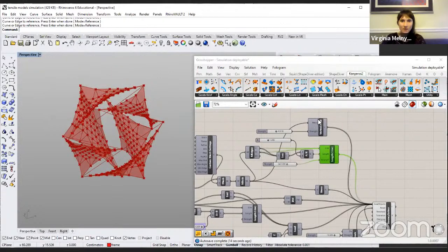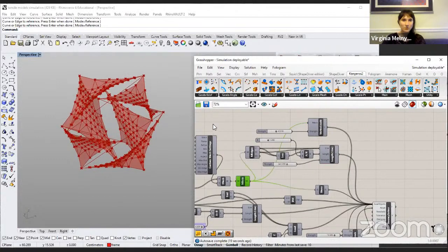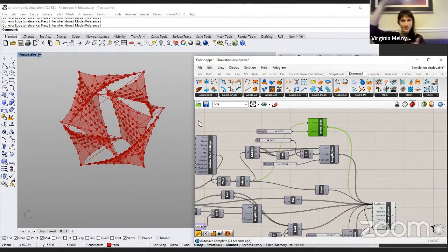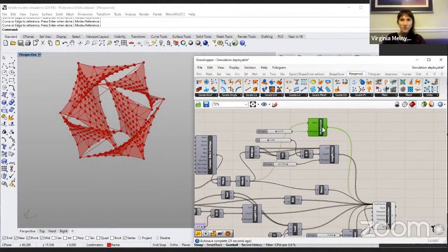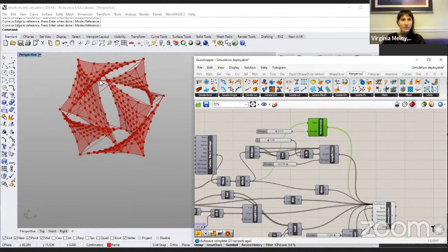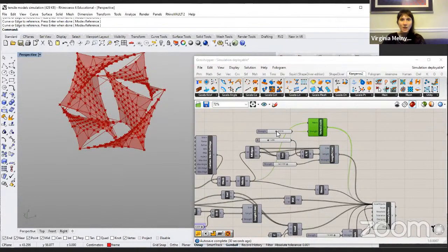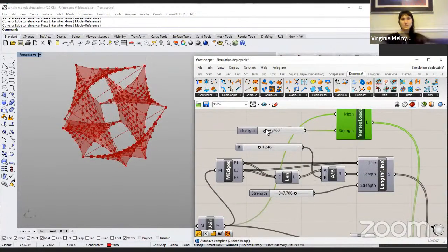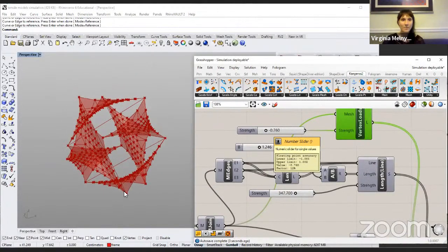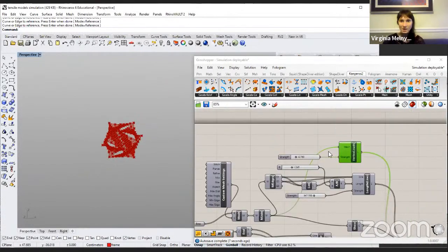And then this one goes for the whole mesh as a load. So we want to have some gravity on this, right? Because otherwise it does kind of float away and disappears. So this is actually just a load onto all the vertices of the mesh just to create some gravity, since we still have that. And I make this a negative strength because obviously gravity goes down as a negative strength. But you have to be careful because it might fall forever unless you add a floor.